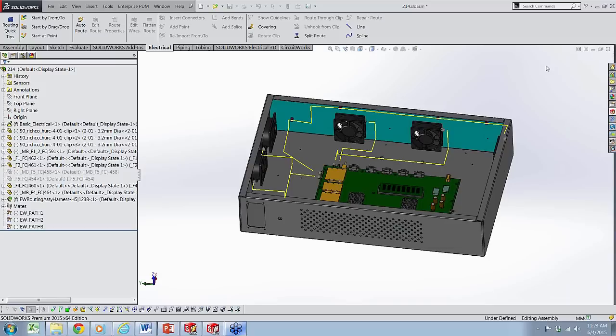In the bill of material, you can include parts information, but if I understand your question correctly, if you have pins information from an Excel that you want to import, this is not possible. You cannot import pins information from an Excel. You can import the symbols information. We can import an Excel spreadsheet for manufacturer, but then you will have to define your terminals and circuits.